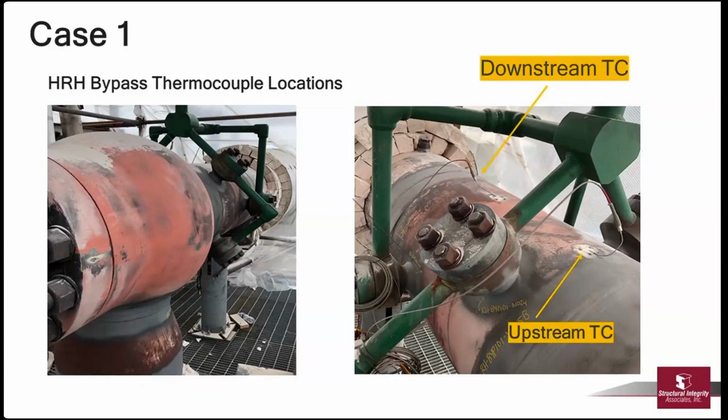All right, so jumping back. These are pictures of actual spot welded thermocouples at one of our installations. I think the previous discussion pretty well covered the use of those. Just a comment on the use of these being safe to use on the grade 91. Back when I was with an OEM, we actually sectioned up a section of spiral fin welded 91 tubing to look at the depth of the weld of the fin to the tube.